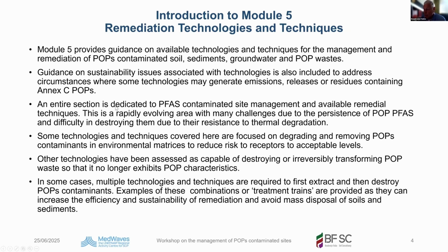An entire section is dedicated to PFAS, as I told you, contaminated site management and available remediation techniques. This is a rapidly evolving area with many challenges due to the persistence of POPs, PFAS, and difficulties in destroying them due to their resistance to thermal degradation. So besides that they are water soluble and form large plumes, they are also resistant to thermal degradation.